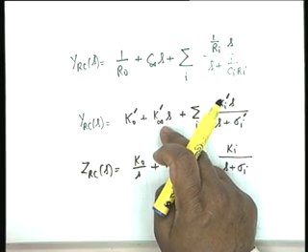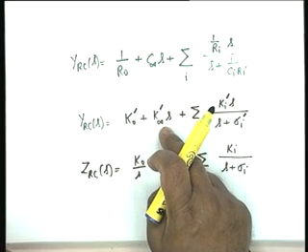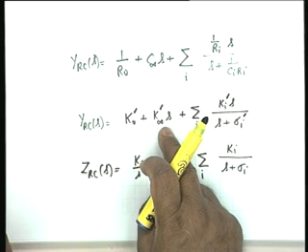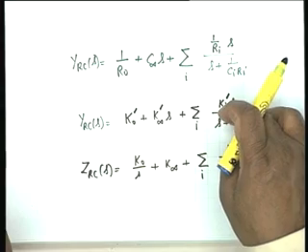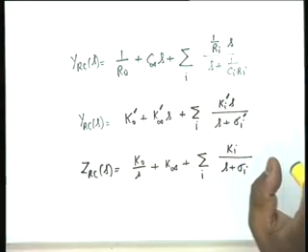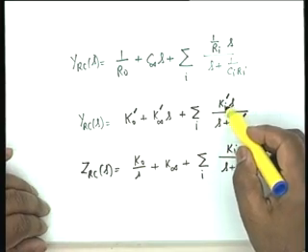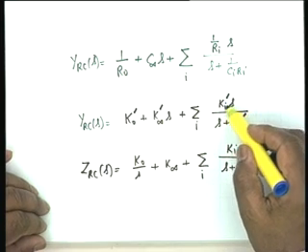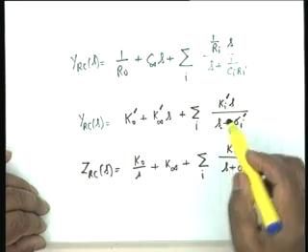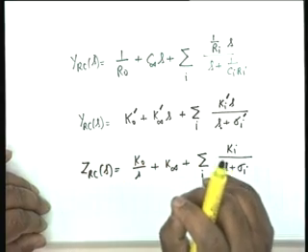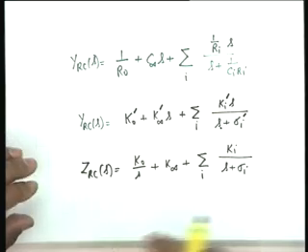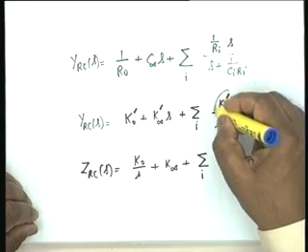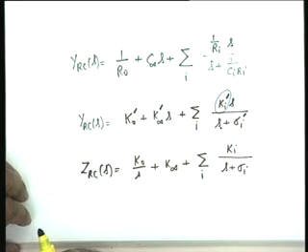If it does not have a pole, if K infinity prime is 0, then what is the value at infinity? Constant. It is K0 prime plus summation Ki prime, because at S equal to infinity it is the highest power term Ki prime S over S. So at infinity, YRC infinity would be simply K0 prime plus summation Ki prime. But the most important deviation is that this Ki prime is not a residue. Do you understand this? It is not a residue.